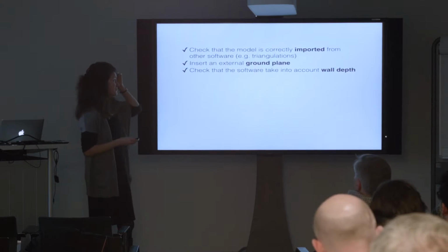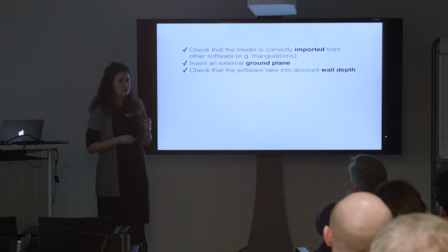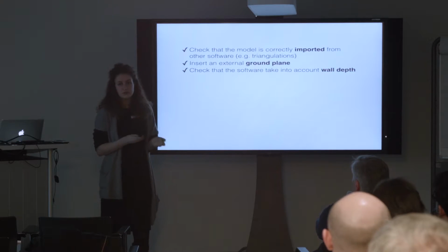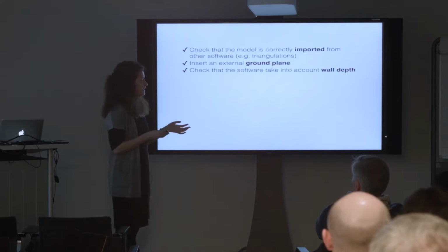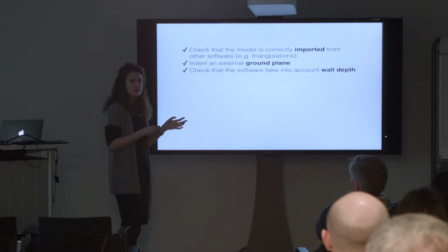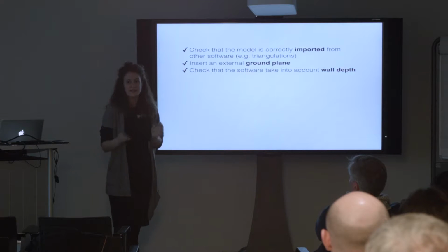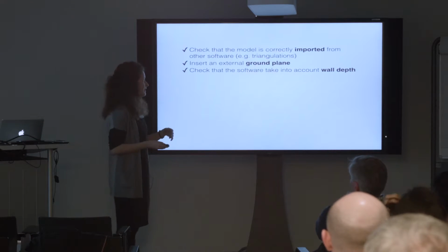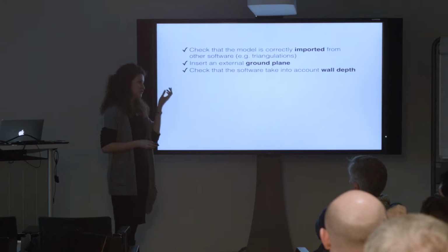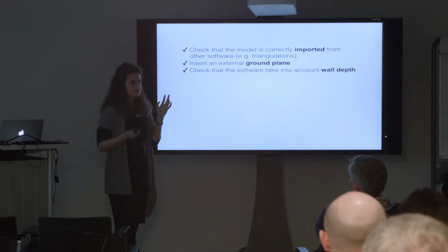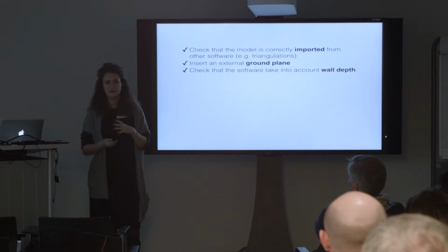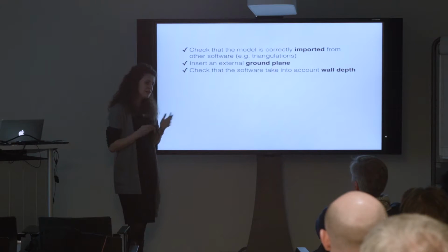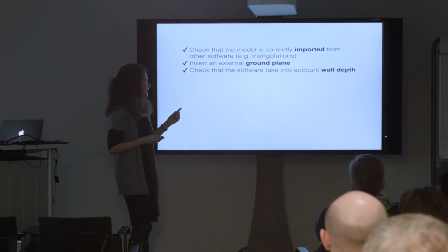So first, on the geometry: if you import the model from another software, it's good to double check that everything you were seeing in the previous software, you're still seeing in the software that you're using at the end. And also, you should simplify it. If you have tons of triangles instead of a small curve or door handle or whatever, you should try to clean it up.